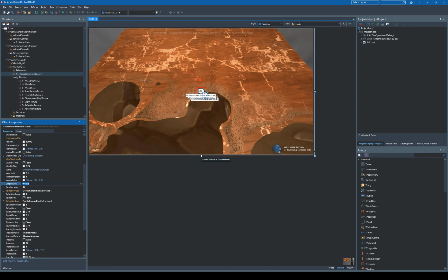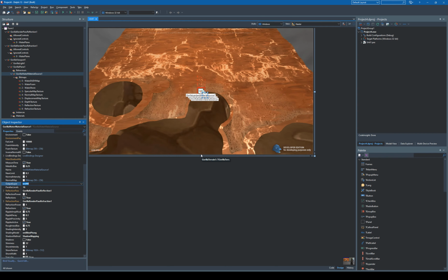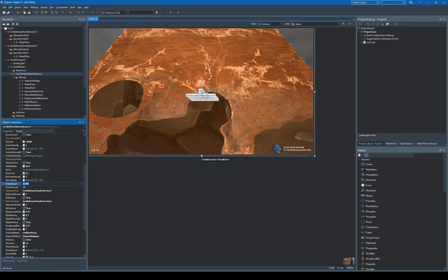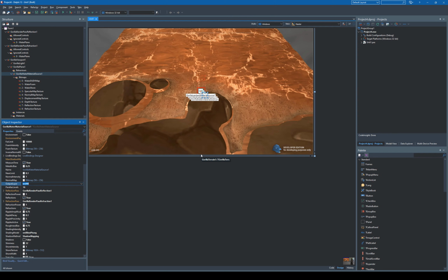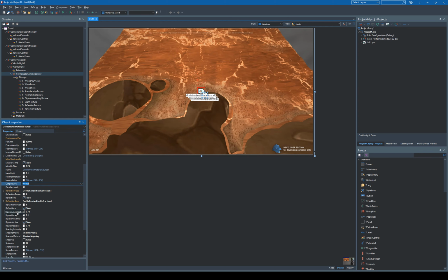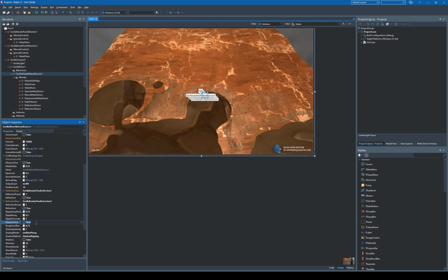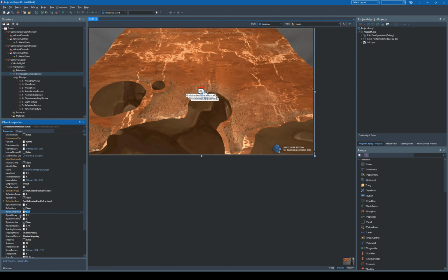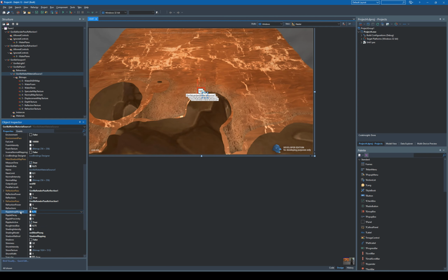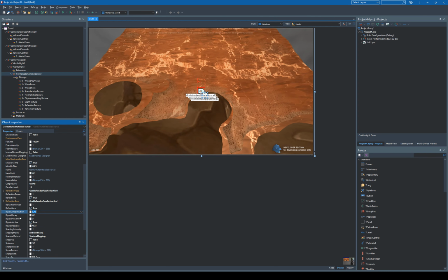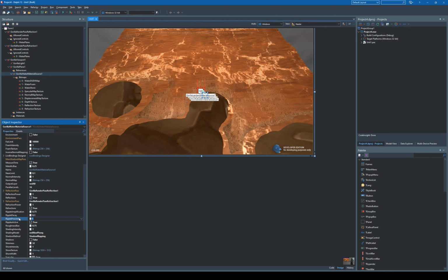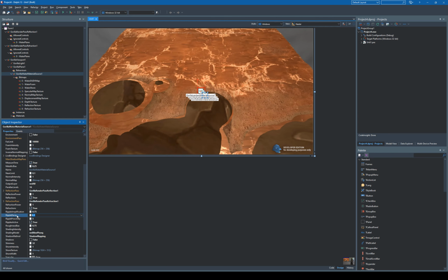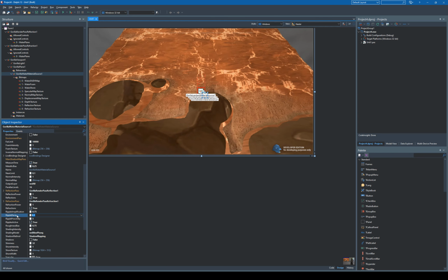One property of water is that it can produce ripples. Our Gorilla water shader provides functionality to add those ripples to the surface. Before it can be used, it needs to be activated by the ripples active property. Then you have further settings to configure the output. Set ripple amplification to define the height of the ripple, and the ripple proximity defines the basis value for the width of the ripple. And the ripple decay tells the shader how fast a ripple will end.